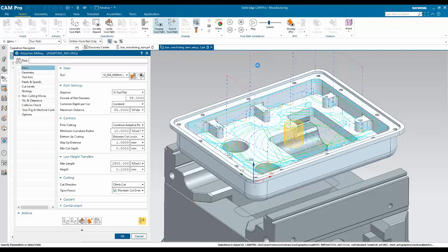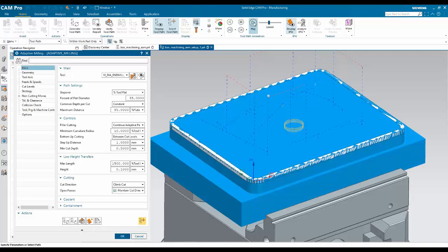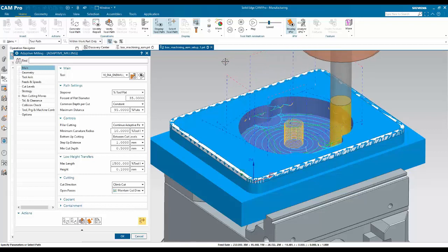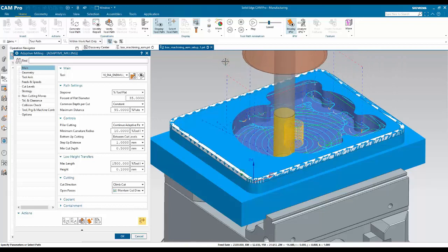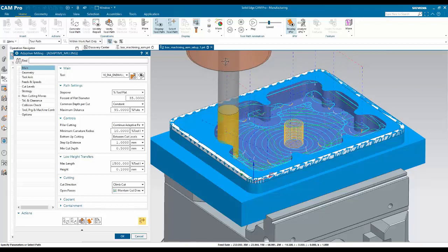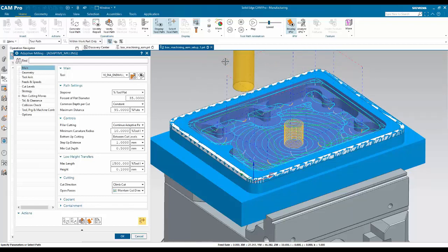Let's play what's actually going to happen in here. Quite simply we can play that. And so it tries to do a whole helical move out as far as it possibly can. Then when it can't do a helical move anymore, it does nice looping moves in, trying to maintain the volume of material that's being machined. And in so doing, you're able to increase or maintain your feed rates, because you're not gouging or digging into corners and loading the tool up in corners.